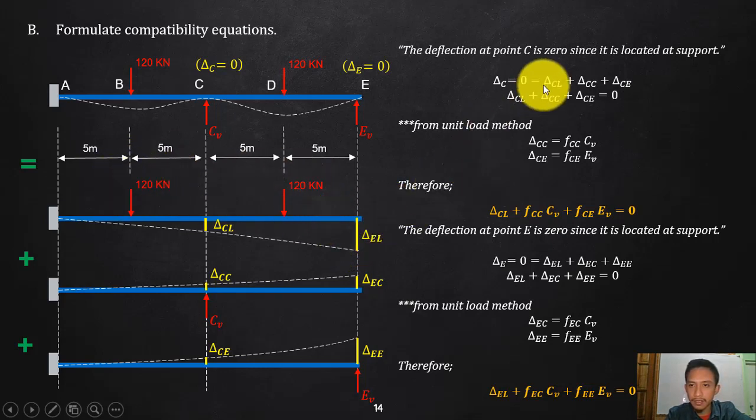So I can solve that one. Deflection at C due to the loading, and deflection at E due to the loading. So this will be my 2 equations here. Again, I will be explaining that one later. And then, of course, apply the redundant at CV. You will be having this deflection or deformed shape. So these are negative.